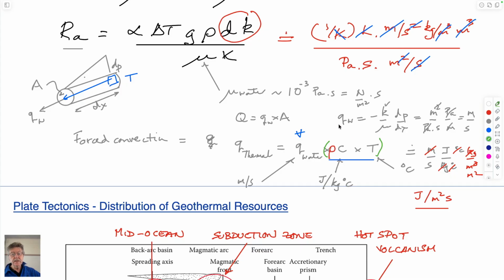The water that is circulated goes through from the injection well to the recovery well. It comes out at an effective volumetric flow rate, which is just a velocity multiplied by the cross-sectional area of this tube. And so this now becomes the flow rate of water, which represents the ability to convect by forced convection water out of the system, and convect with that water, heat being piggybacked on top of it. So this is the mechanism by which we need to do that.